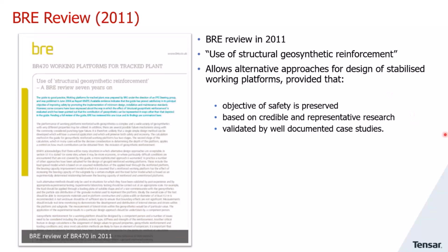Many Tensar proposals are used as an alternative to the illustrative methodology in BR470. We will look at whether our T-value working platform design method satisfies these criteria. We need to demonstrate that the T-value method satisfies the requirements if we are to follow the BR470 advice.